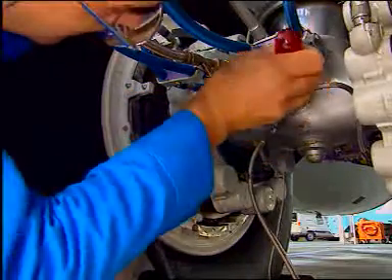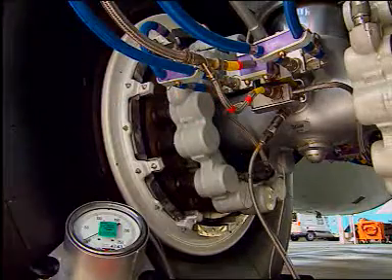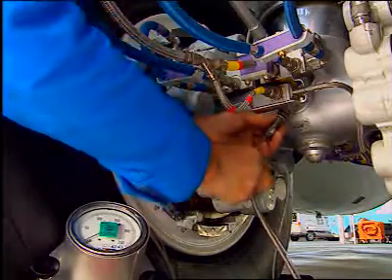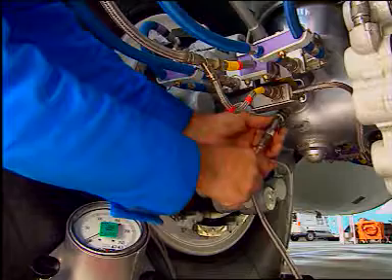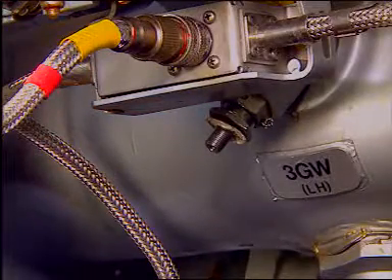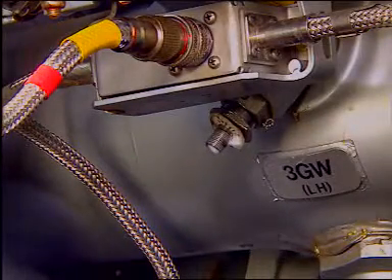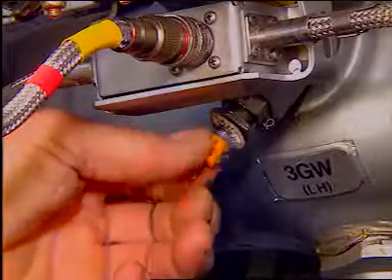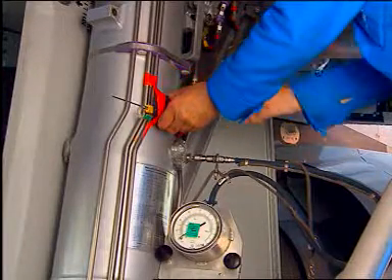On the bottom charging valve, torque the valve to the preset value. Remove the charging equipment. Use special materials to do a leak check of the valve. Install the blanking cap. Remove the thermometer.